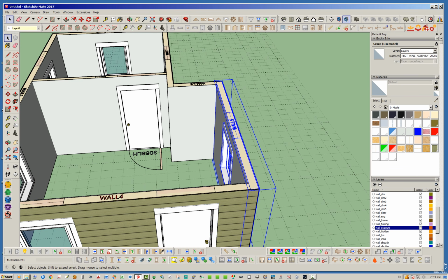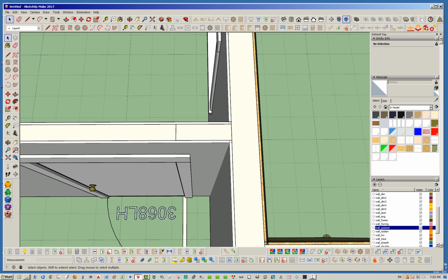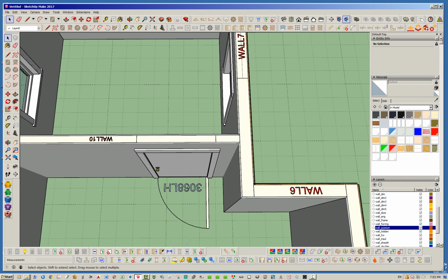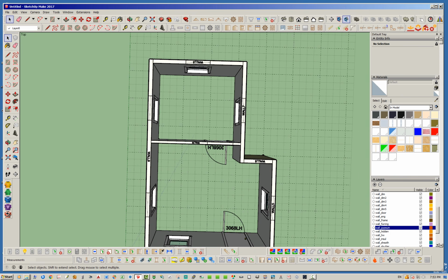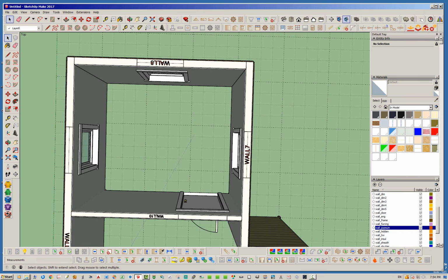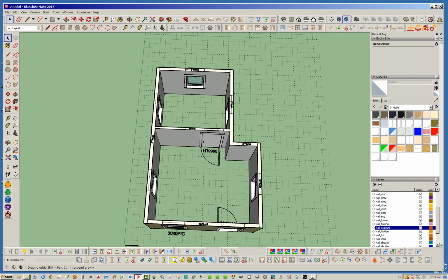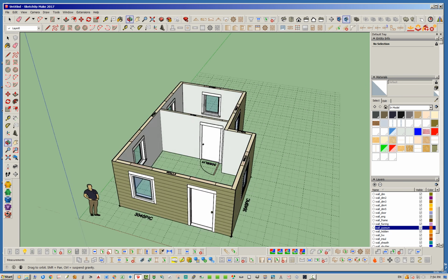Okay, so the only thing is as you've noticed, each one of these is a separate assembly, and because it's a separate assembly, you have a situation here, like if you're doing a plan view, a top down, you have these edges that end up at the end of the walls, and so it's not like one contiguous border all the way around, which you may want to show that way in layout or however you do your plan views and such.